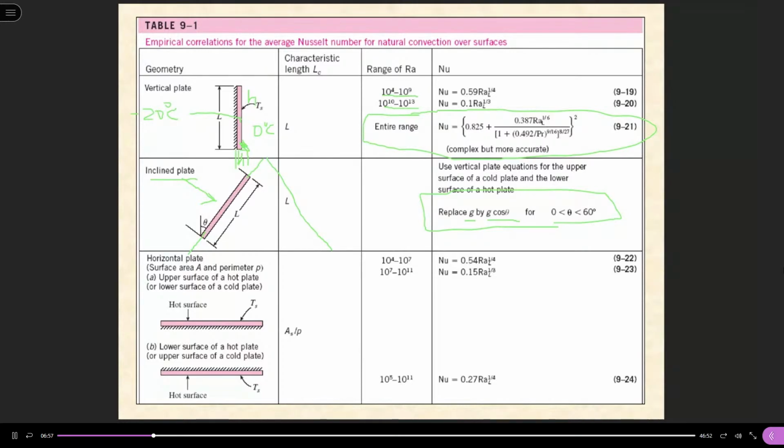How about in some cold climates, you use a heated floor for heating. We call it floor heating. What you do is bury some pipes under your wooden floor, in which you flow warm water. This will make your room very cozy, very comfortable. Then we have this equation. It depends on the Rayleigh number. First calculate the Rayleigh number to see what the value is, then use one of two different equations.